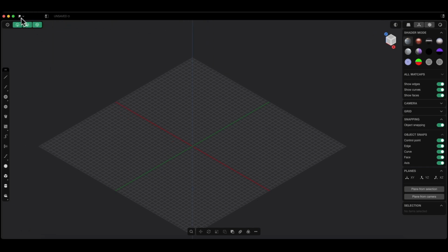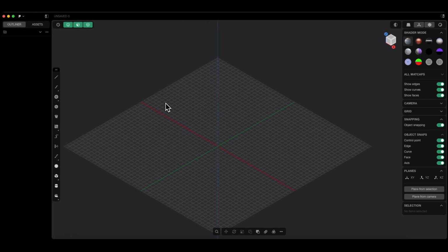And when it comes to creating 3D models in Plasticity, as I mentioned, we have an approach based on direct modeling, and here everything we do is done in the workspace. We will start by creating a simple shape. We will create a rectangle, and when it comes to drawing a rectangle, we have several options available here. At the moment, the corner rectangle command is active. However, with this command, we have a small arrow, and if you hover over this command and press and hold the left mouse button, other commands will appear that allow you to create a rectangle.